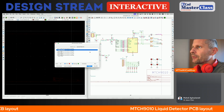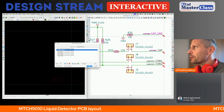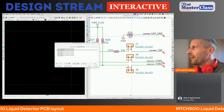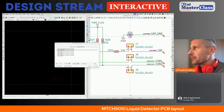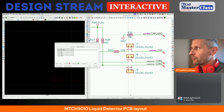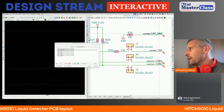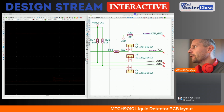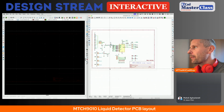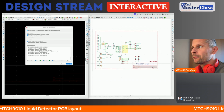Yeah. So instead of 3 electrodes, there are 4 electrodes because cap ground, as we discussed, will be grounded. And for the sake of clarity, I use the 0 ohm resistor in series of this signal to isolate it from the ground, because I don't want to mix the ground label and the electrode name label. So we are ready for the component layout.